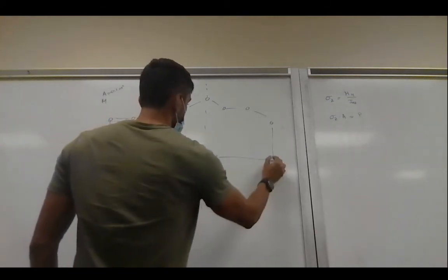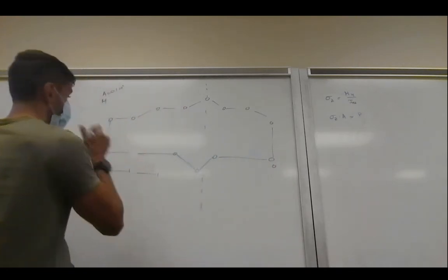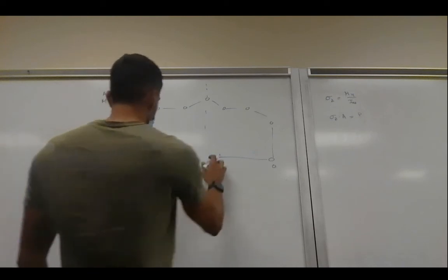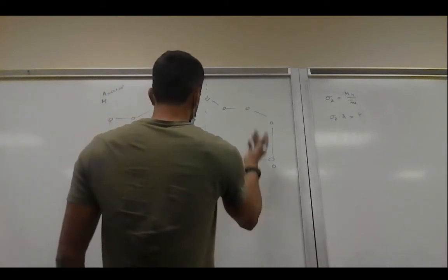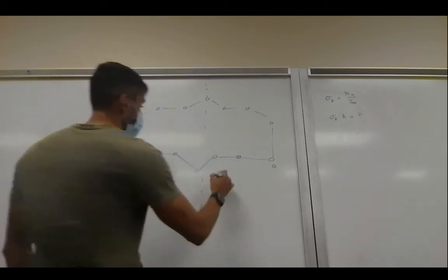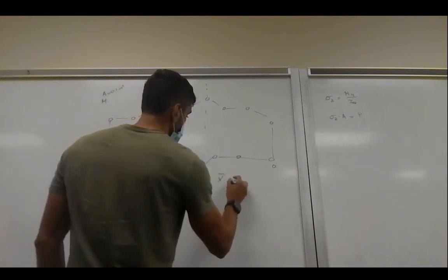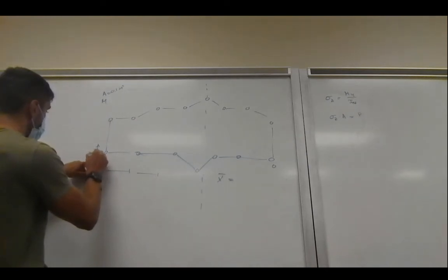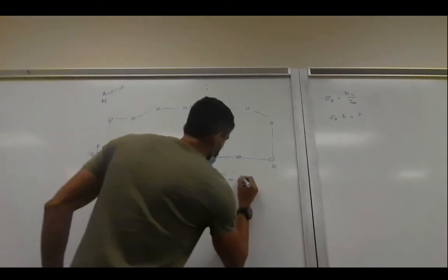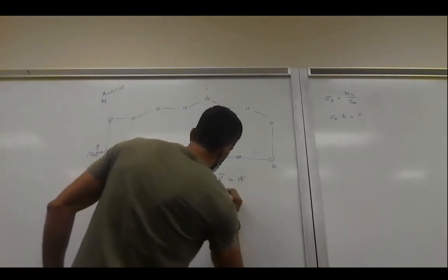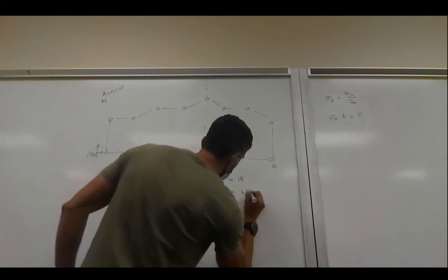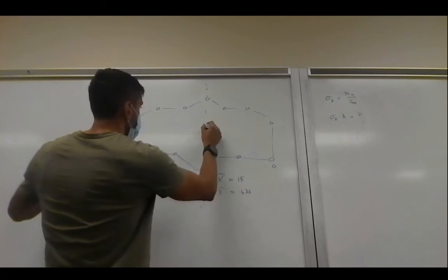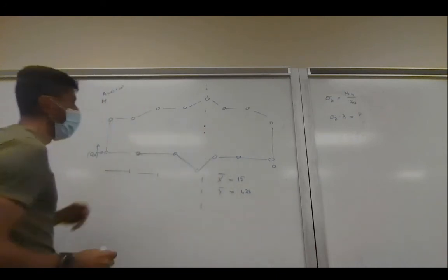I think it was something like this actually. Because I know it was 15 apart. So this is 5, 5, and 5. So this is 5, and then we have here 1 as well. Doesn't matter. So you know that x bar is in the middle. So from this point of view, if this was our origin, 0, 0, it would be 15, and then y bar would be 4.33 from the distance, and I will put it just above the center.